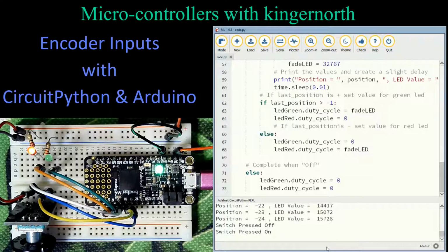I talked about earlier that you're actually getting 4 different signals in from the AB pin combination. That's why they call it a quadrant encoder or an incremental encoder. And you just want to be able to take your time and work your way through it. And if you want to create your own code for that, you're certainly welcome to do it. You can create your own code based on those 2 pins. You can also use the simple helper files, and it saves you probably 30-40 rungs of code that you would have to type in yourself.